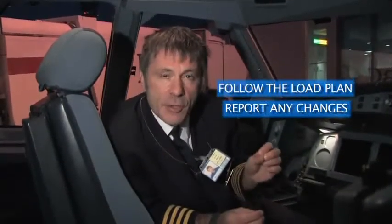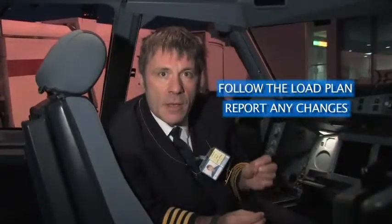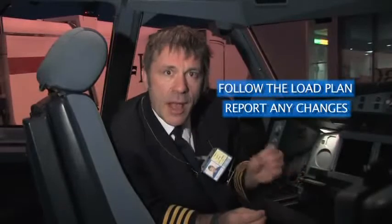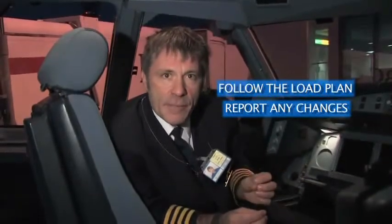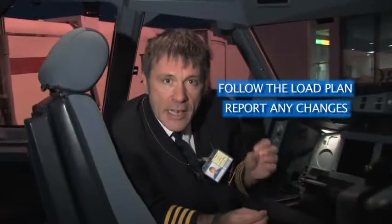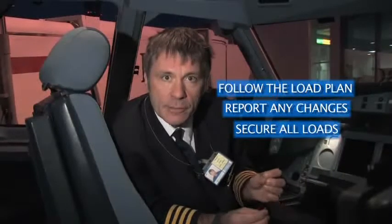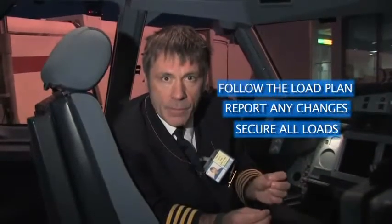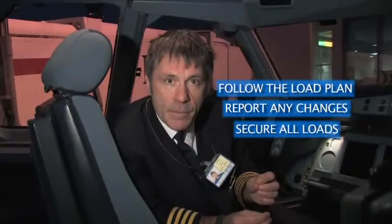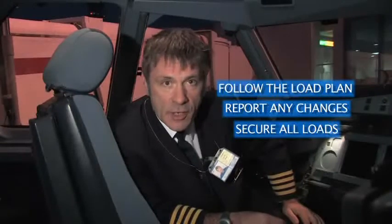If you think that the load is unsafe, if you think that it's more than it should be, don't just accept it. Ask and tell somebody. And thirdly, and very importantly, any loads you do put on an aircraft should be secure. Make sure the load is secure. Make sure the locks are in place. Make sure it's strapped down and it will not move under the stresses and strains of flight.